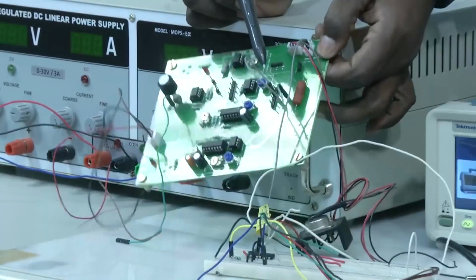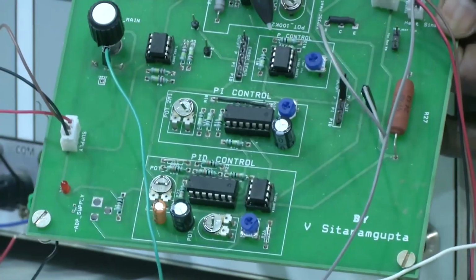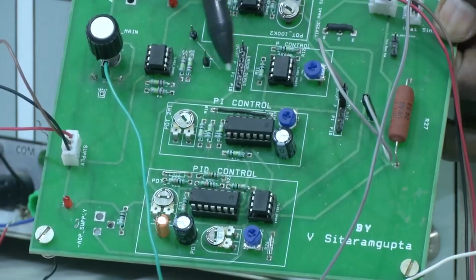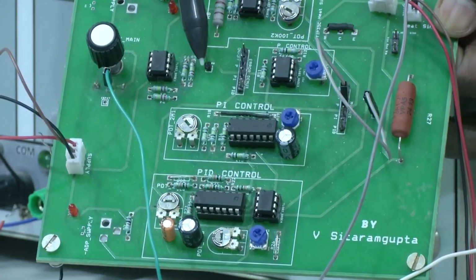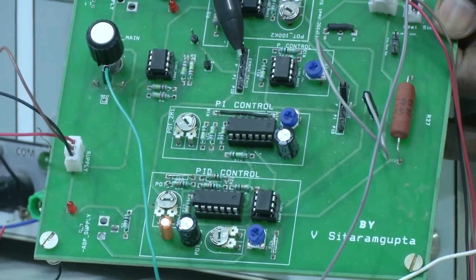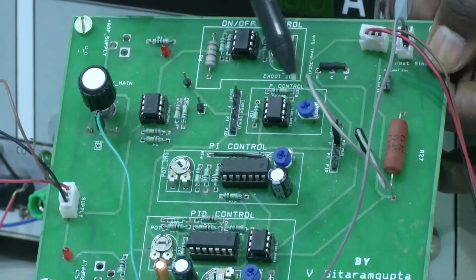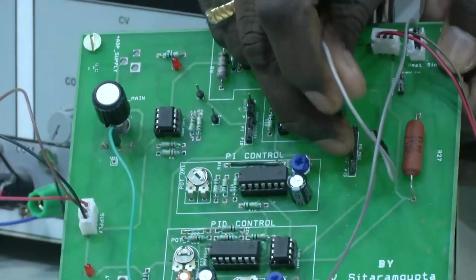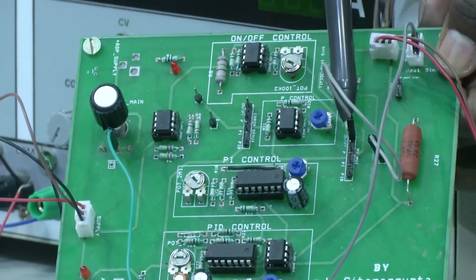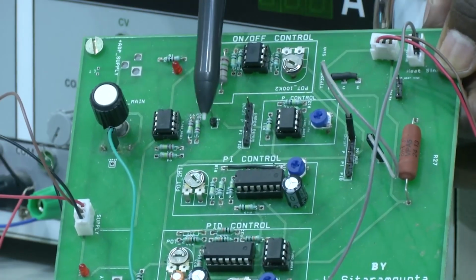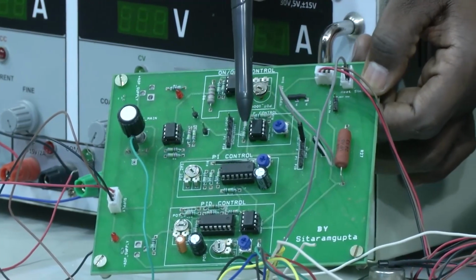Now, if you see the board closely, by using these jumpers we can decide which controller we want to connect, right. This is an error output. Suppose I want to use the on off controller, I can connect the output of this to the on off controller input, and then it gives an output here, right. If you connect to the on off controller, the output should be connected like a mux and demux. If I want to use the P controller, we have to connect the jumper wire between the error output and the P controller, so that this particular block will be used, right.